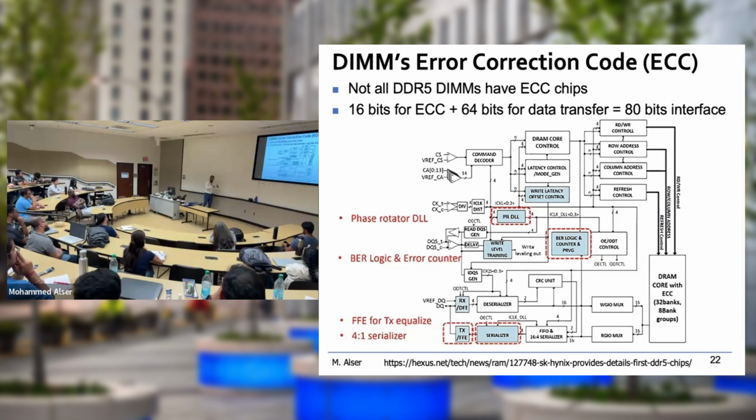So basically, we fit more capacitors in the chip itself, meaning those 2 rows are really nearby each other. So anything happening here is going to impact the nearby rows. And by doing this really quickly, you're going to erase the data or flip the bits. If it is 1, it will be 0. If it is 0, it will be 1. And this is kind of hacking the hardware because you are hacking the data itself, right? You are altering the data itself.